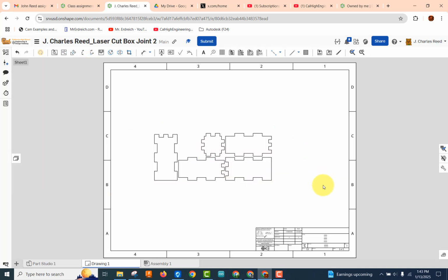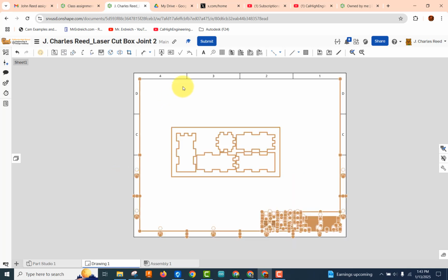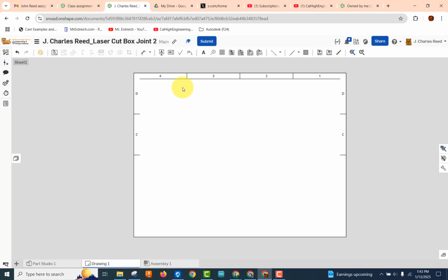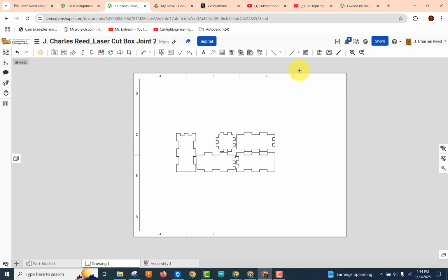Now when we send it to the laser, everything it sees it's going to look to cut or engrave. So we want to go from the lower right to the upper left and grab everything except the stuff we just put in there. I just grabbed it and pressed delete on the keyboard and I grabbed too much, so I Control Z out of there. Let me be a little less ambitious and more careful and just grab it carefully.